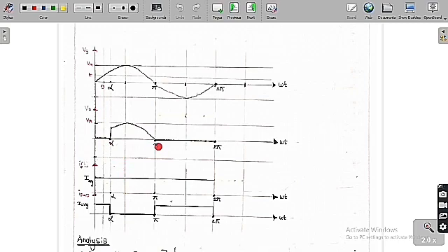But after pi, what is going to happen is the current is always constant. Now a reverse voltage, meaning a negative voltage, is going to occur across the thyristor in this region, so it will be open circuit. Then again the freewheeling diode is going to conduct.